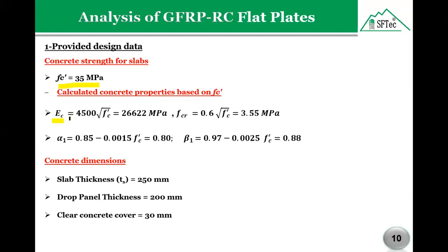So Ec equals 26,622 MPa, and the fcr equals 0.6 times the square root of f'c also. So f crack here equals 3.55 MPa.